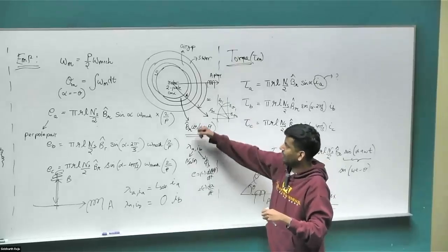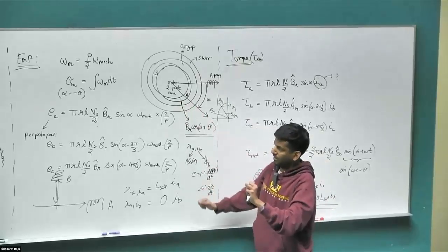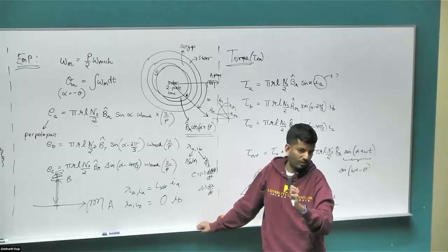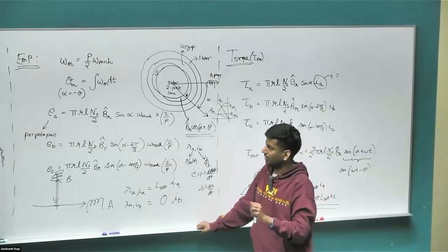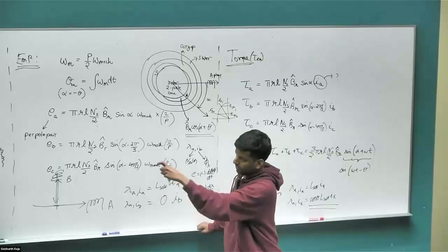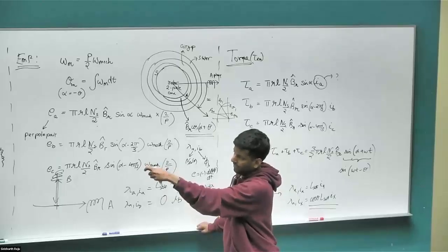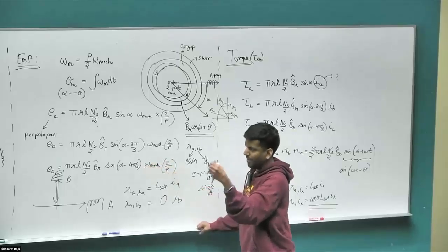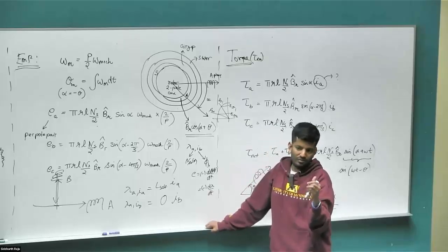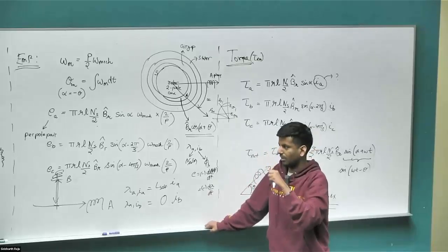Alright, so this magnet is going to set up its own magnetic field in the air gap that's completely independent of the stator magnetic field. So there are two independent magnetic fields set up in the system. The first magnetic field is captured by the LM part, and hence the term magnetizing, because basically we're magnetizing the stator. It's making the stator behave like a magnet, the LM term that we have there.